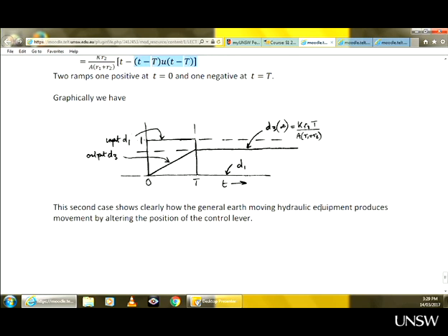Okay. So effectively, in this case, if you want to return your cylinder back into neutral position, first you push forward and back to neutral, then it stops moving. But to come back to neutral, you have to pull the stick back and again forward. And I don't know if anyone has any experience in driving bulldozers or any excavation machinery, that's how it works.